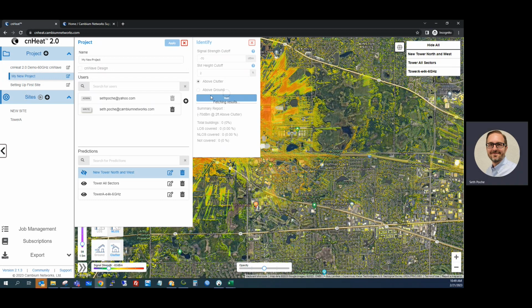The other thing that's really nice about this tool is it's a true kind of apples to apples comparison as you're trying different things. Maybe you're looking at a new tower and you're considering a 150-foot rad center versus a 200-foot rad center, or you're considering maybe running CBRS alone or CBRS with 5 gigahertz. You can run all of these what if scenarios, and then you can see the difference that each one makes. And so you might find that raising the height of the install on the tower only produces maybe 5 more customers that you would cover, in which case maybe it's not worth it, especially if you have to pay a greater lease fee.